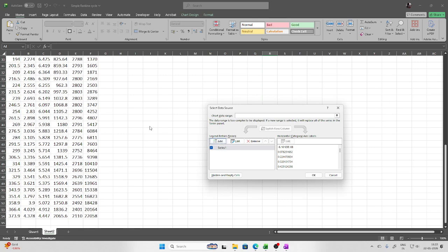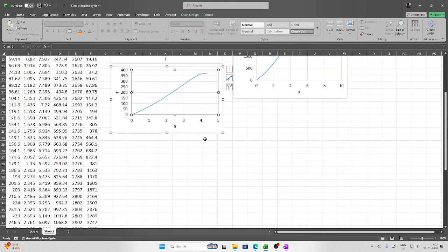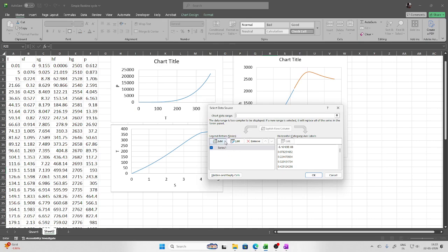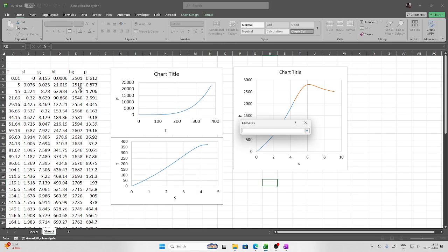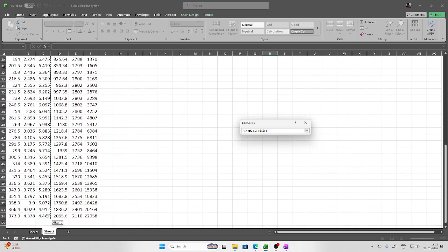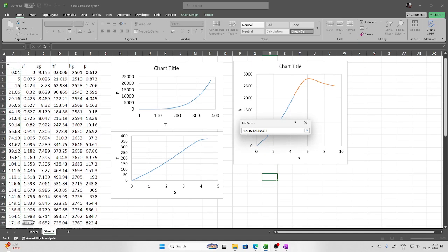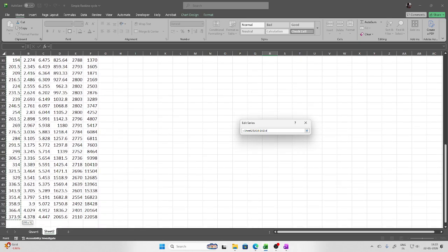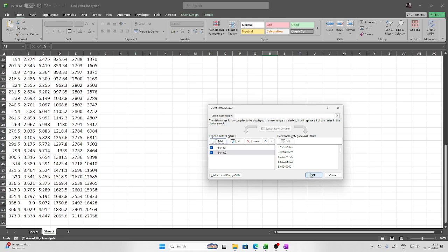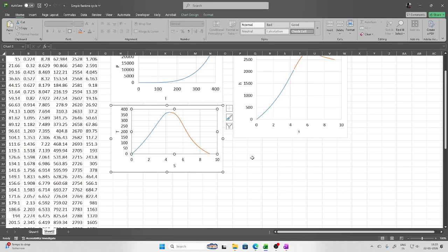And then if I say okay, this saturated liquid line will come. Again, I have to select data, then add, then in the x-axis entropy will come, but this time the saturated vapor entropy will come. And then on the y-axis, the same temperature will come. This is the one. Once this has been done, say okay, and our plot is ready.